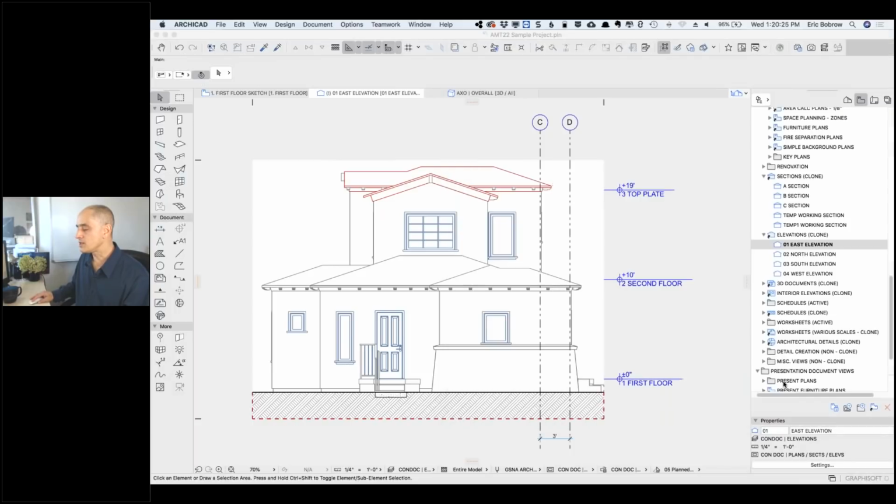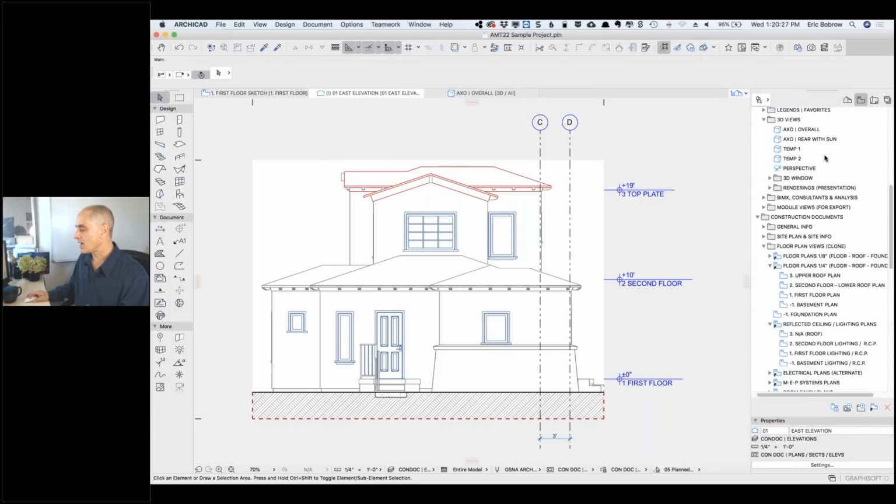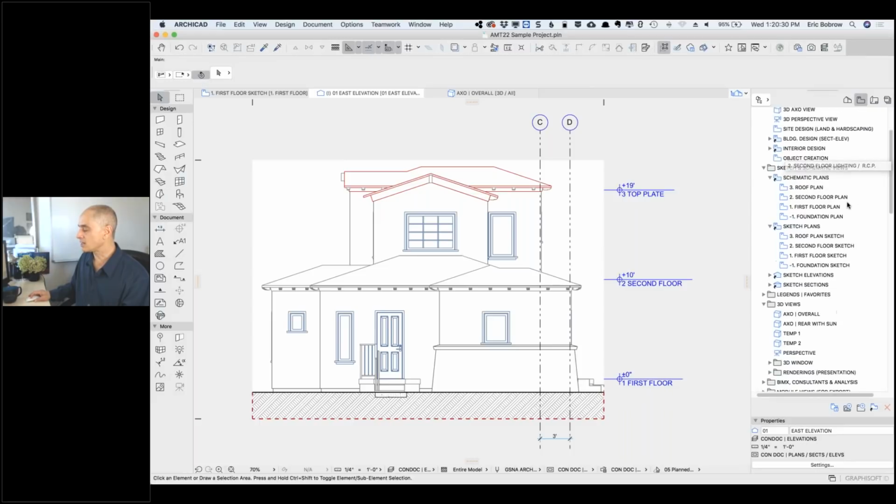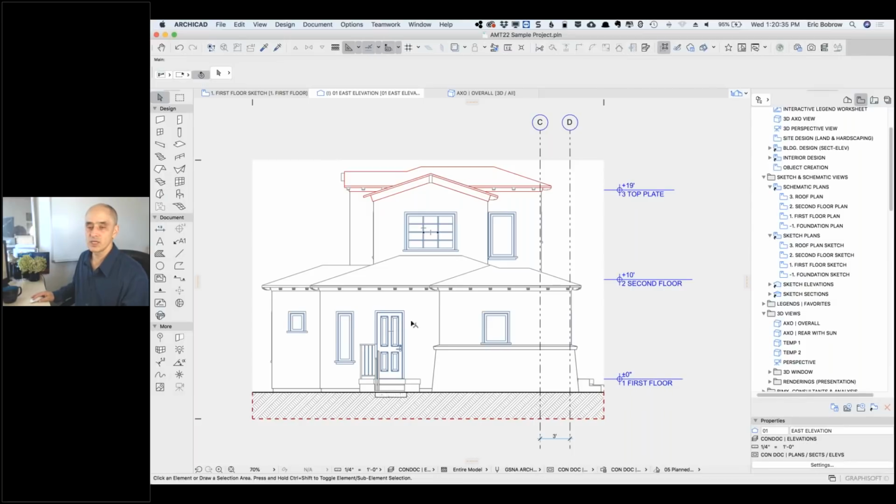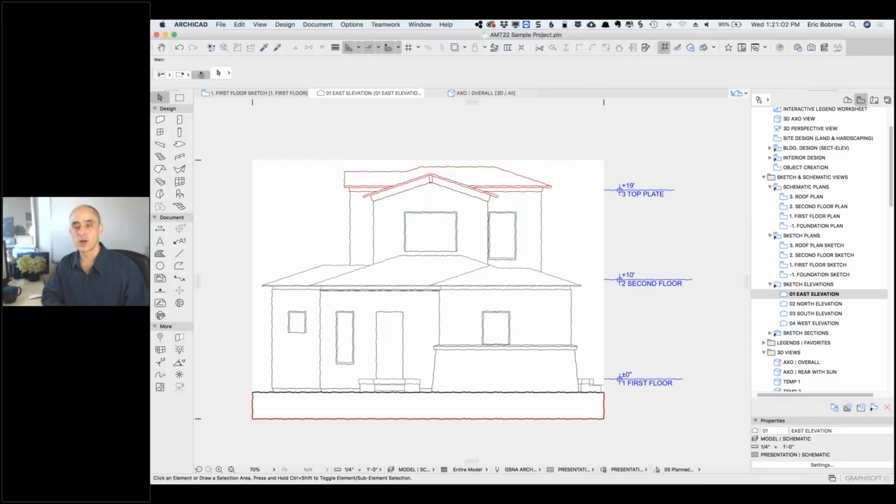Now, having done all of these options here, let's take a look at the one that is schematic level. Now, look at this. You can see the windows and doors have some level of detail, which is fine. I mean, it's good for most purposes. But suppose you wanted to have an elevation that was just simpler, like when you were first doing the building and you don't want to say how many divisions the window has or even whether it has a sill. You simply want to have an elevation. Let's see, this is the east elevation here. That's simplified. So how did we get this?